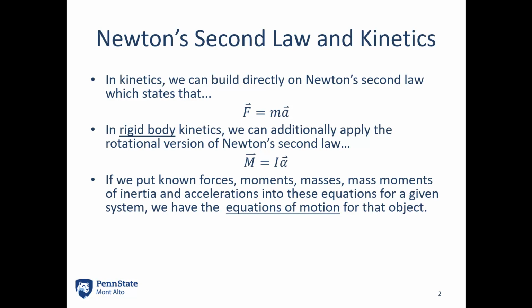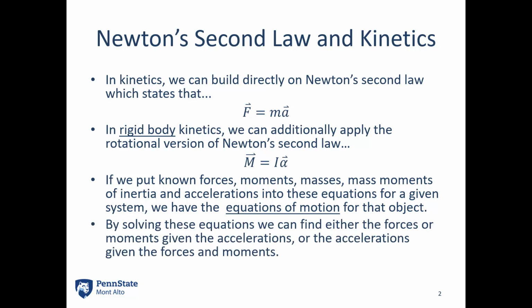If we put all our knowns, forces, moments, masses, mass moments of inertia into these equations, we wind up with what we call the equations of motion for that object. So by solving these equations, we can find either forces or moments given accelerations, or accelerations given forces and moments.